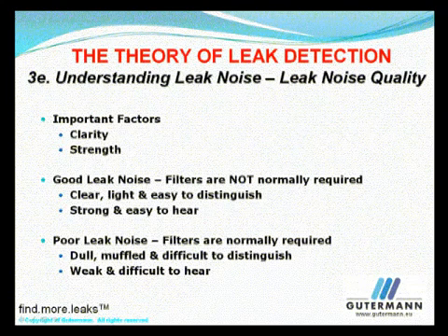Leak noise. Quality of sound. If there is a clear and loud leak noise, location of the leak should be straightforward. If the leak noise is dull or muffled, you will need to use the filters to tune into the sound of the leak. If you are unsuccessful during the day, you should return at night when pressure is higher, the leak noise is louder, and background noise is reduced.